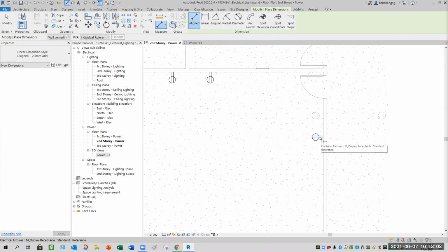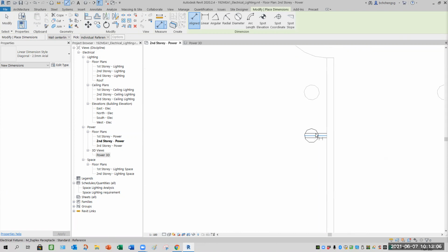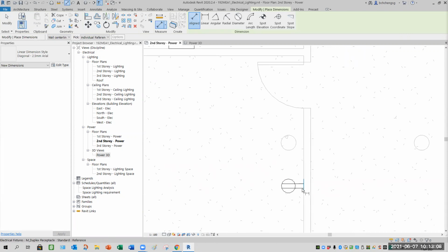Why? If you select from here first, you see when I start to do tracking, there's one point here and one dot here. See this? And you can see there's another center line. If you define or snap incorrectly, you're not able to do the dimension. If you base on the default, from here, you try to do the dimension, see, not allowed.